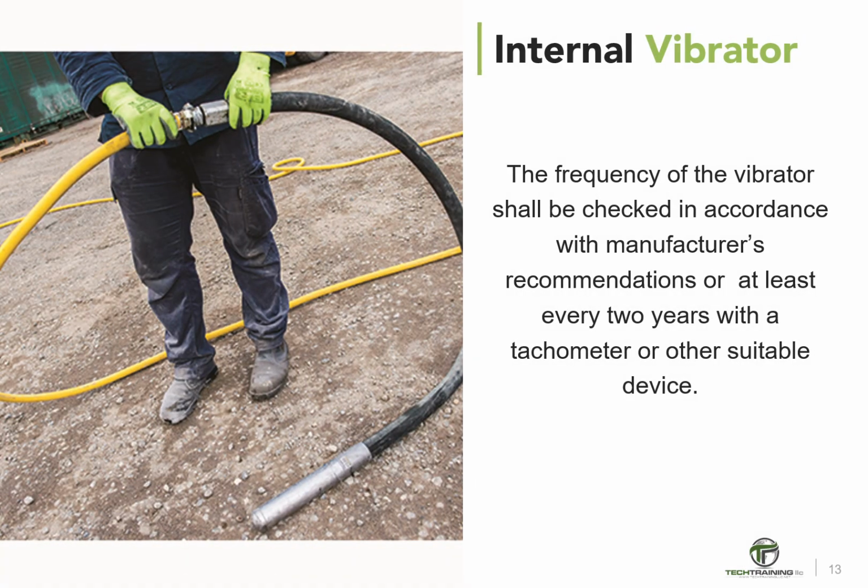The frequency of the vibrator shall be checked in accordance with the manufacturer's recommendations, or at least every 2 years with a tachometer or other suitable device.